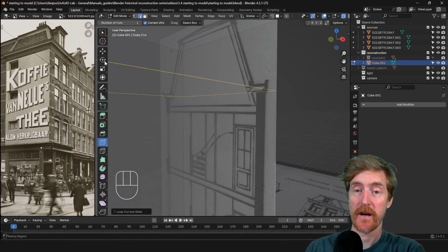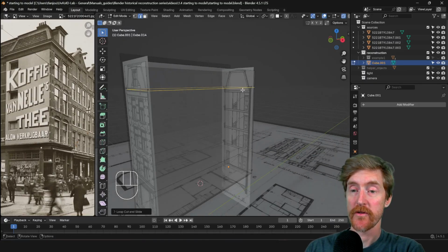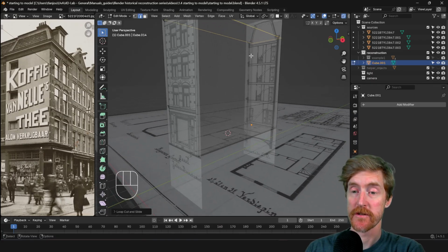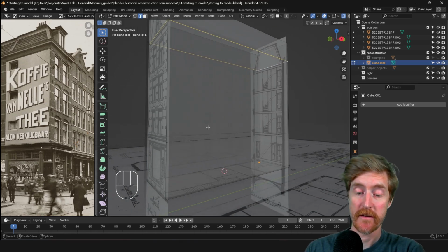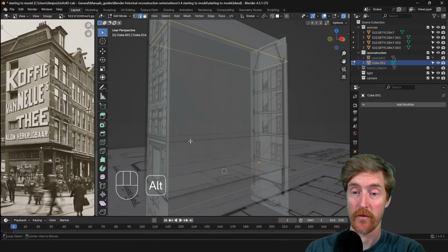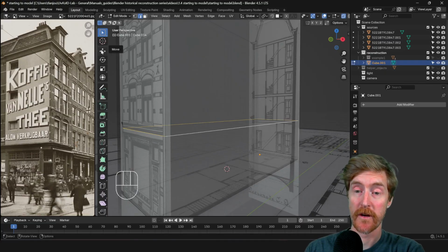Okay, so I will now deactivate the loop cut tool by selecting the select tool again. So what if you want to reposition these loop cuts? Then you have to select all the sides of the loop cut. And there's one quick way to do that, and that is to hold Alt on your keyboard and select one of the edges on the loop. And then it will automatically select the connected loop. So now I can move the loop to another position if I want to.